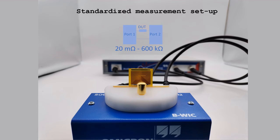Here is the measurement setup for the second configuration. Our inductor is connected to the specific standardized kit. This kit has 3 ports. The first port is connected to port 1 to generate the waveforms. Other ports are for port 2 to measure the waveforms. Port 2 is split into 2 ports to improve the measurement accuracy. One port is to measure the magnitude and the other port is to measure the phase. With this setup, the valid impedance range is within 20 milliohm to 600 kiloohm.